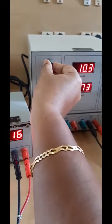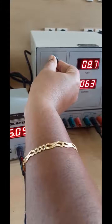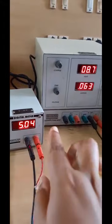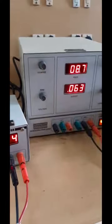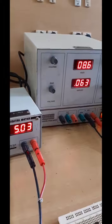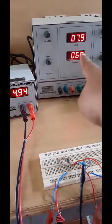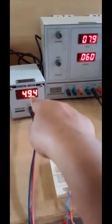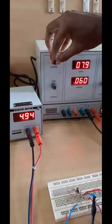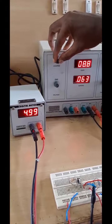Whenever we are changing this input voltage, whenever we are lowering it, the output voltage is 5 volt itself. So whenever there are fluctuations in the input voltage, the output voltage is regulated to 5 volt. When the input voltage is 8 volt, the output voltage is 4.94, and whenever we are increasing the input voltage, now it is 9 volt, then the output voltage is 5, there is a slight increase.